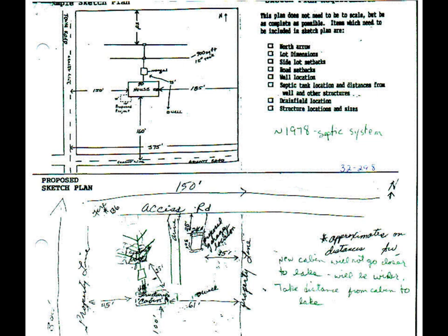They went to take a core sample, and I immediately stopped them, asking, "Well, why are you taking this from a low wet section of my property? My septic field is up over there." They then took a core sample to 84 inches deep. There was no evidence of redox until they reached 74 inches deep. The field depth was 72 inches and above, so the absence of redox, the soil, and by extension, the field,